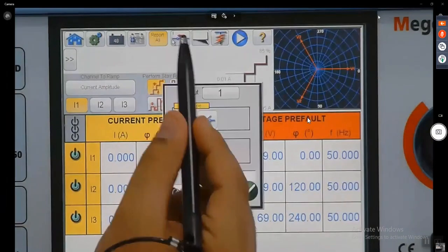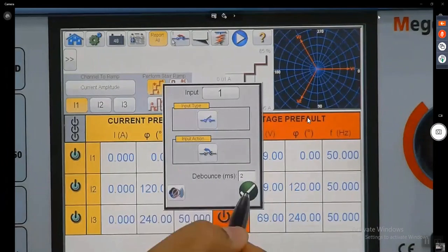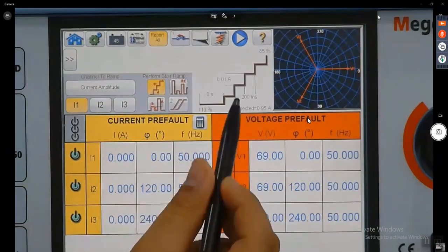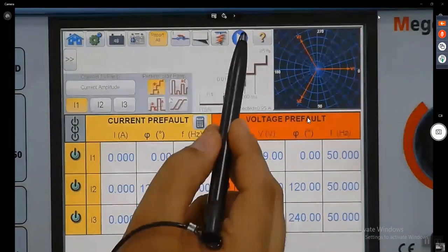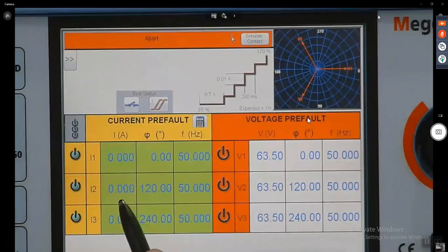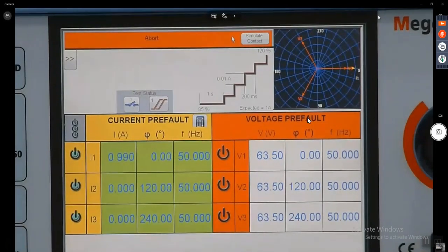I'm waiting for it to be closed, not waiting for it to be open, as this is a ramping or drop off test. So I will click start the test, still starting with the pickup by increasing the current automatically, and then decreasing it for the drop off.